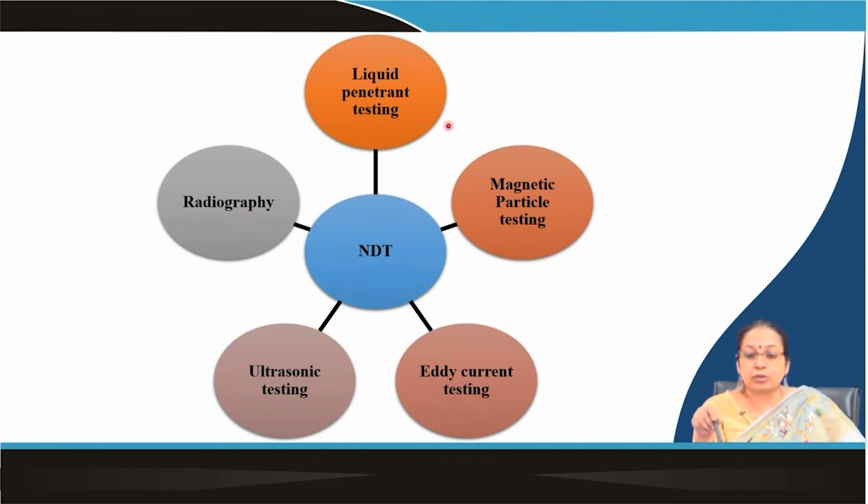So, if you just quickly go through the individual techniques, you will find that each technique has its own limitations and advantages. Advantages are there, for example, simplicity. Among the non-destructive testing based techniques shown here, the liquid penetrant test is the easiest one, which may be applied for the detection of surface defects, surface porosities, and surface micro cracks. Those things can be determined by liquid penetrant test.